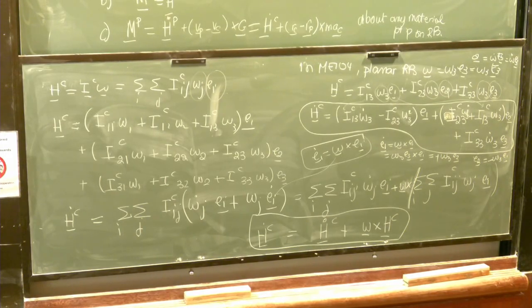What is going to happen to the washing machine? Is it going to rotate smoothly? No, it's going to shake and jump because this uneven mass distribution, these non-zero products of inertia, are creating moments not just about E3, the axis of rotation, but about the other axes, E1 and E2. So you see they're creating moments about E1 and E2 and not just E3. So that's where they come in physically. Another example of this is that if you're driving a car and the axis of the wheels is off center, they add small masses to the wheels so that the center of the wheel is the axis of the car, or else you're not going to have a smooth ride. Okay?